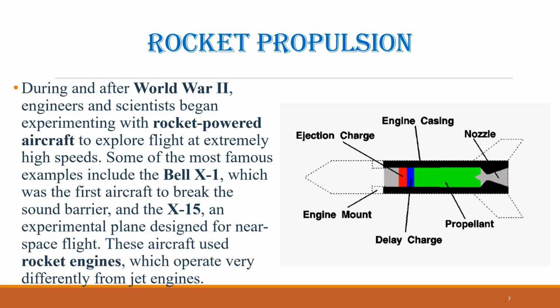In contrast, a solid rocket has its fuel and oxidizer mixed together into a single solid block known as the propellant grain. This solid propellant is stable under normal conditions and will not burn until it is ignited. When an igniter provides a source of heat, combustion begins at one end of the propellant, producing hot gases that escape through the nozzle to create thrust. The burning process moves steadily through the propellant, forming what is called a flame front.